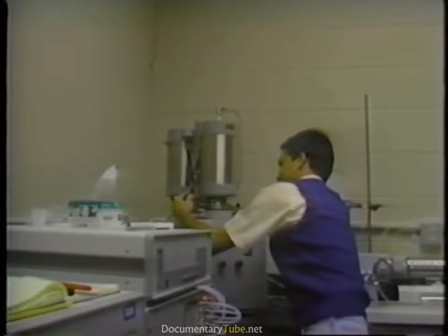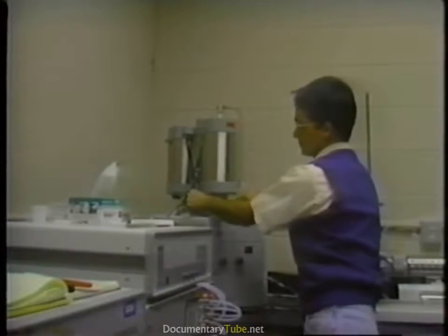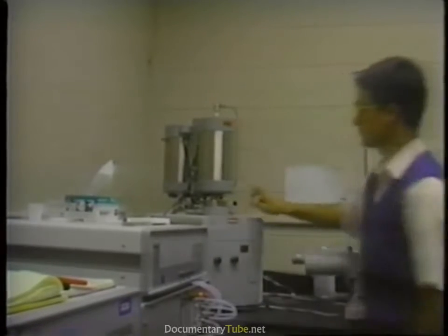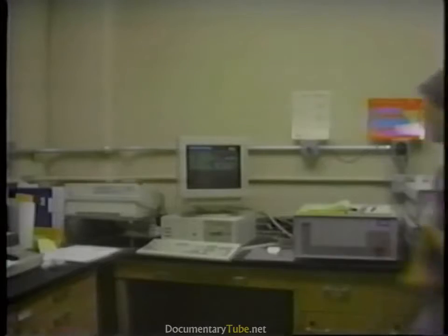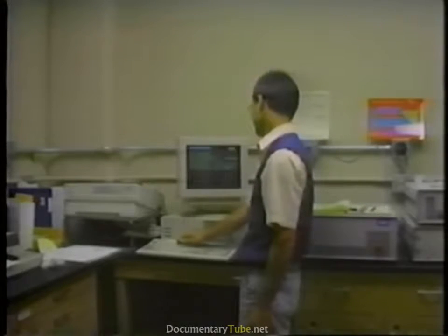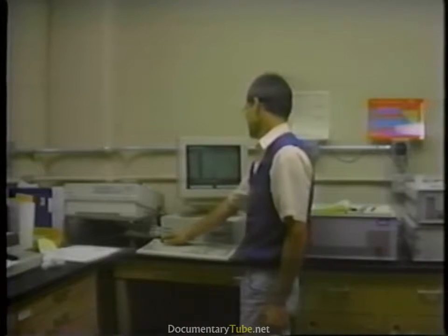The free water in a sample is driven out by heating to 105 degrees Celsius. At 105 degrees, the sample is dry, but still retains its strength. The water involved in the hydration reactions is chemically combined with the cement and can be driven out of the sample by heating to 1,000 degrees.